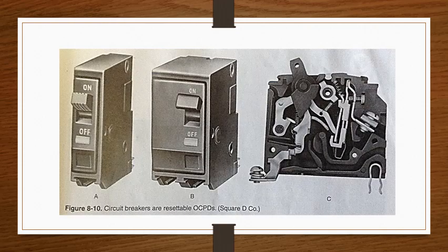Circuit breaker types. A single pole breaker serves a 120 volt circuit. A double pole breaker serves a 240 volt circuit. Typically, these breakers are plugged or bolted into the service panel and connected to the ungrounded wire of the particular circuit they are to protect. The neutral conductor of each circuit is not connected to the breaker, but fastens directly to the neutral grounded bus bar.